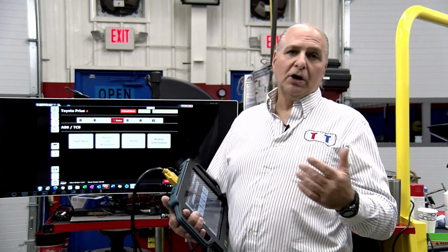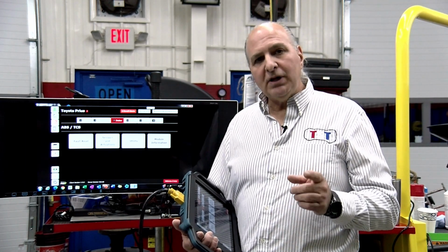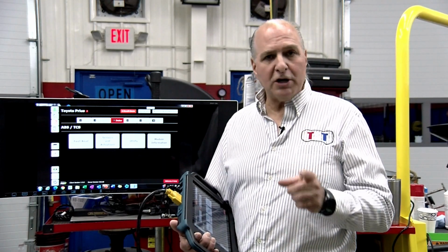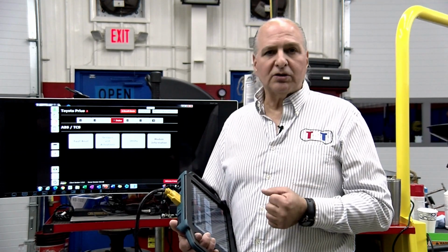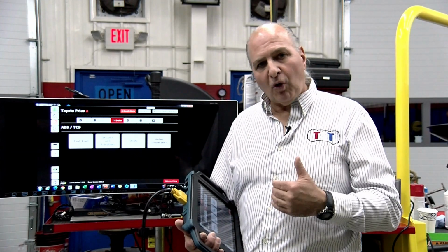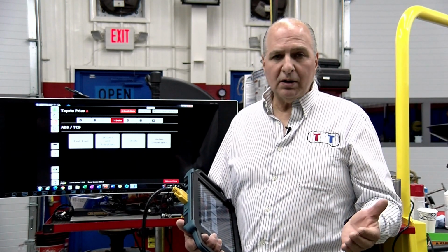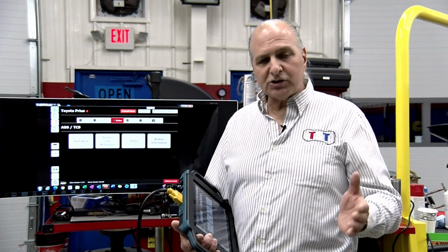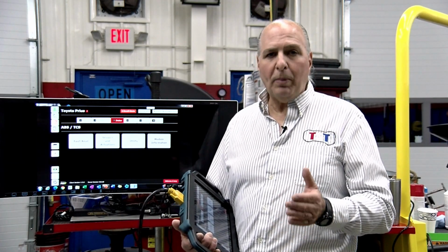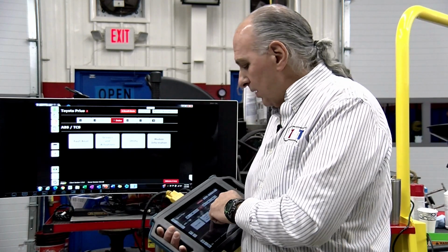So this system is not your typical system where you think you're just going to go in and do a brake job and bleed it. You need to RTFI, read the information, okay? The reason why you need to do that, if you mess up, it's going to take you a little while to get that brake system back working. There's a stroke sensor, there's regular ABS stuff in there, but the system's a little different. Gen 3, Gen 4, and including Gen 1, they no longer have it, they use it in the new ones, and they didn't have it in Gen 1. This was a Gen 2 thing. Again, no power booster, no vacuum, okay?